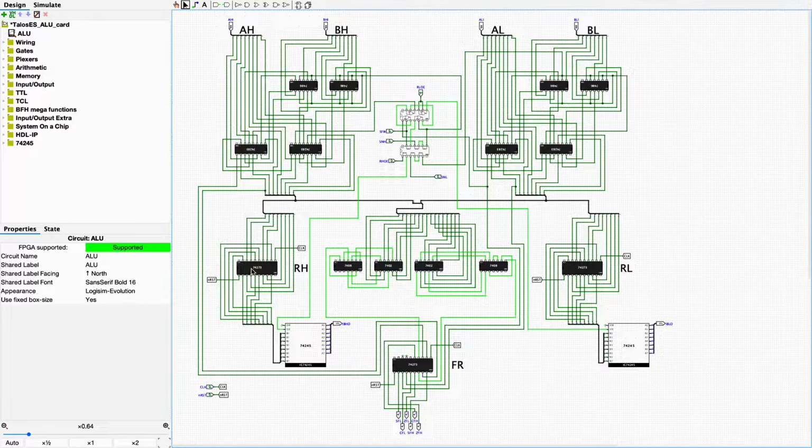And in this case, they will be latched by these three registers here, the result high, result low, and the flag register. Now, the cycle after that, the contents of A high, B high, A low, and B low will already change, because they will be the contents for the next instruction. Remember, it's one instruction being executed every cycle. So you do not have the time to steer the results that come out of the ALU to one of these registers, A high, B high, A low, and B low.